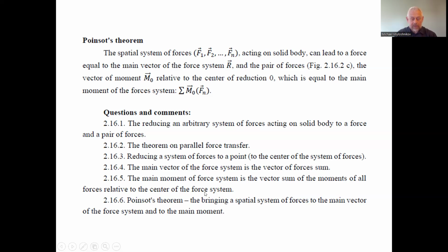And to the same point, we can determine the rotating moment of each assigned force, because when doing the parallel transfer of each force, we have to keep the original balance of the mechanical body. We have to put at the transferring point a balancing system of two opposite forces equal in magnitude to the assigned force of the system, and the opposite one of this couple is put at the reduction point of the system of forces.